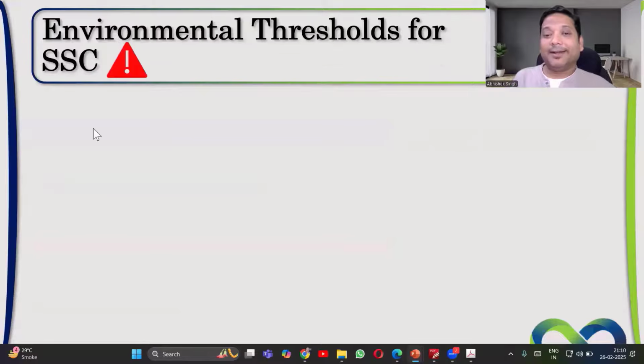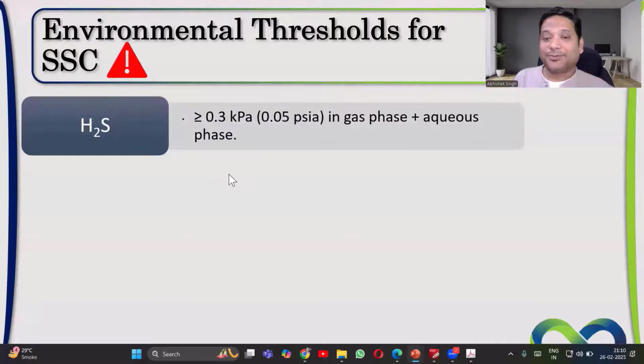Okay, now what are the thresholds for SSC? Now we'll talk about SSC because we are talking about 103. SSC is more discussed and more explored phenomena. SOHIC and HIC are still getting explored. The frequency of SSC is very high, so that is the reason it has been evaluated more, and we have more records of that. HIC and SOHIC have very few records. So mainly we'll see the rules for that.